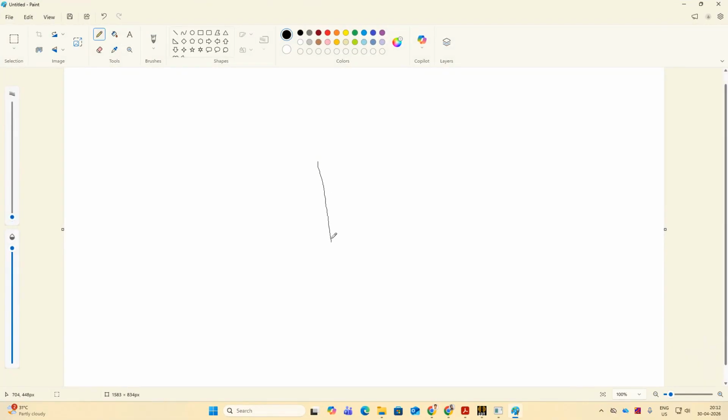So this is our slot. This portion is for the wedge, so it is not for winding. So here I can accommodate winding. Now up to this is a trapezium and this is a half circle. Now this length is bs1, this length is bs2, and this height is hs2.